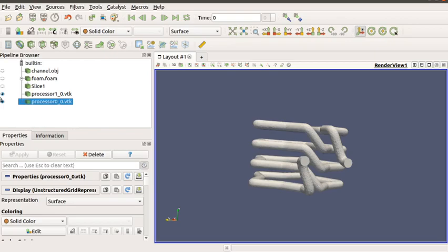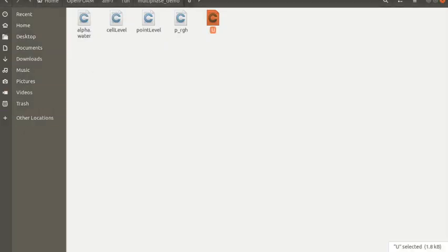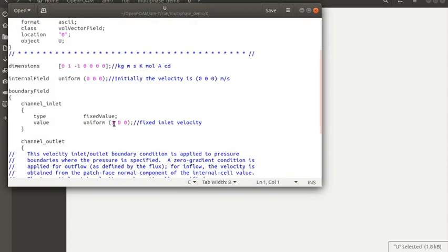If we are not giving the proper direction, the solution will not converge, and it will take a lot of time to complete each step of the simulation. So I greatly advise you, before running this simulation, before calling the solver, make sure that the direction of velocity is in the right direction. Otherwise it will not give a good simulation result.